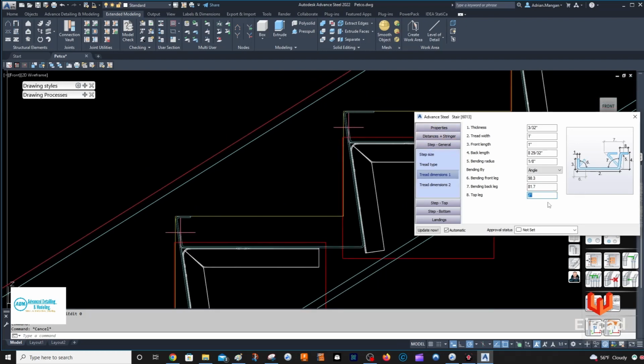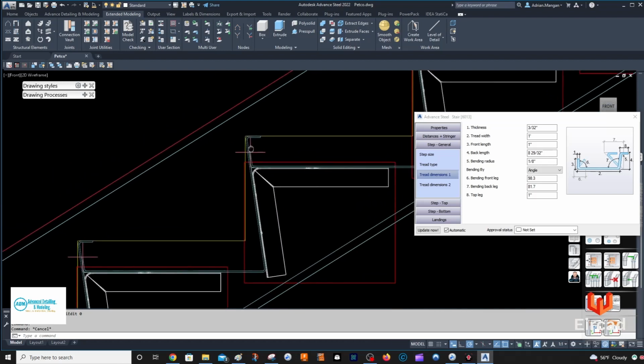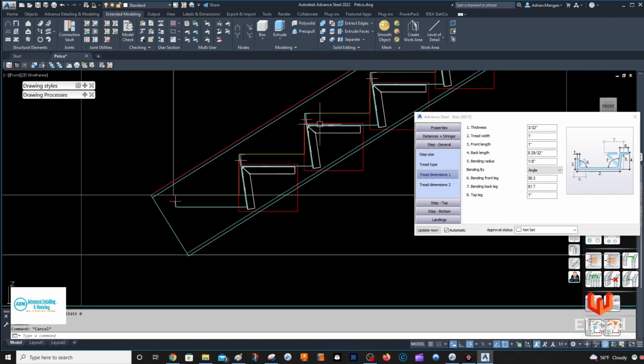So the reason I'm making this short, 1 might even be too long, is you need a nose in here, but I also need to be able to get in to weld this here. So my guys will put the screws in, and then they will reach in here and weld this from the front. So the welds here will be hidden underneath the concrete, and any other welds will be below the stairs.